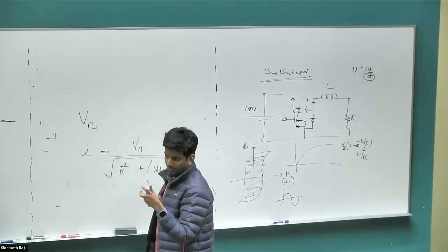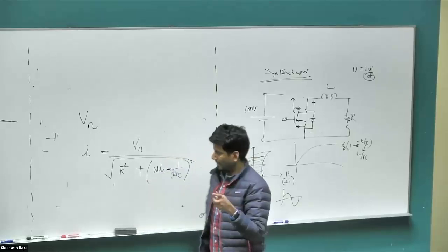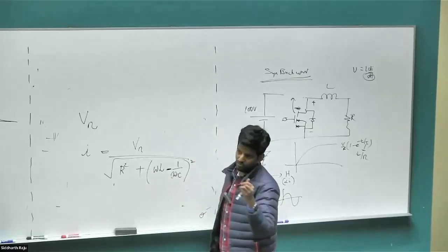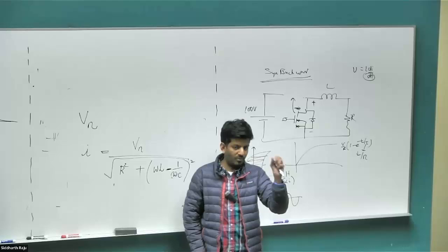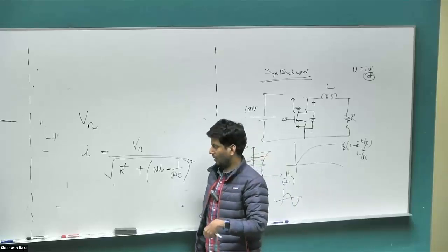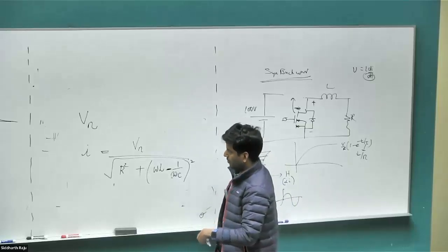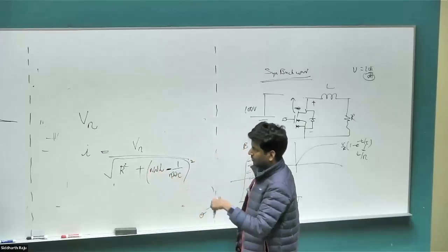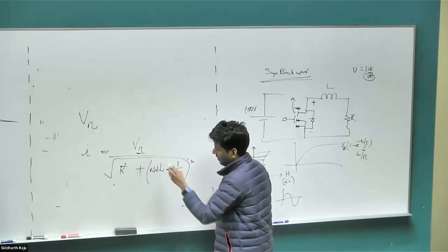So that's the only way we can explain resonance. Because if you get the correct frequencies, these two terms will cancel out and the network would have maximum amount of current. The capacitor components will equally cancel out the reactive impedance component. And again, of course, the n term should be there, depending on which nth component you're considering.